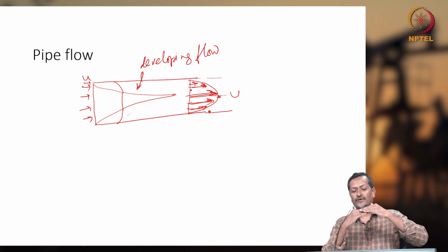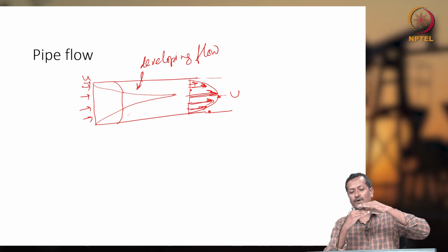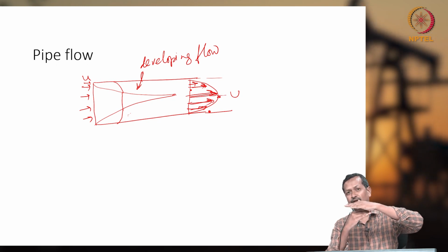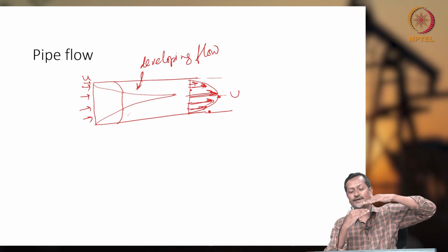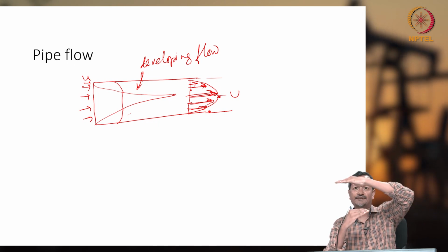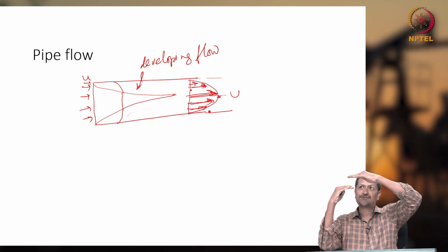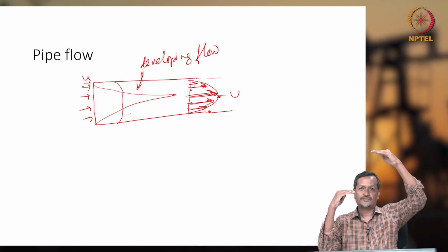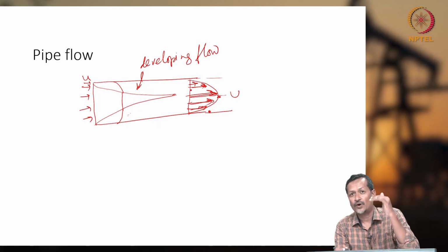And when you are going away from the wall, the fluid particles will be sliding. One layer is here, not moving, another layer will be here, and that layer will be moving over the other fluid layer. So different fluid layers will be moving one by one. That's why near the wall you are getting 0 velocity, but when you are moving up, you are getting higher velocity. Again you reach the center of the pipe, and again as you move up your velocity will go down, and you reach the upper wall of the tubing. So your center velocity is very high, but wall velocity is 0.